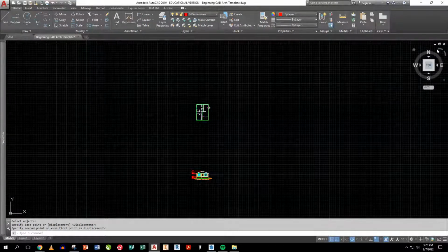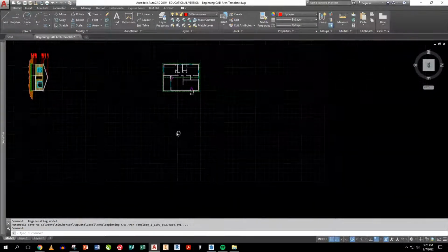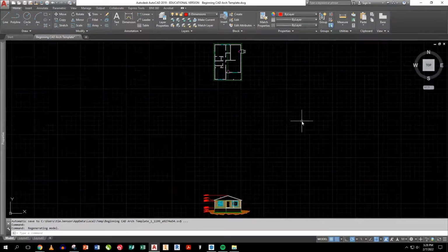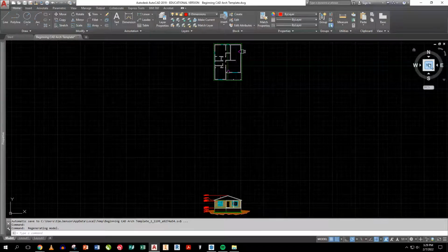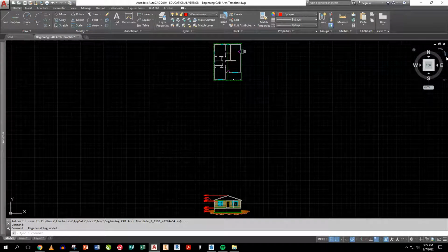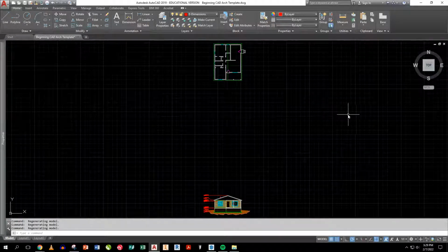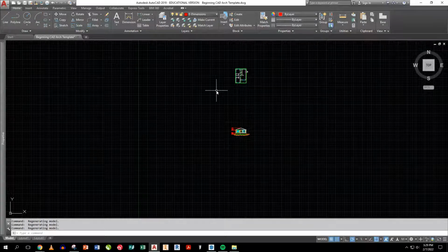There are some students that prefer to do this right here. If you click on the navigational bar, you can actually rotate it flat to you and project flat, and then rotate it back to normal. Okay, do not mess with the cube though. Okay, just a warning, because otherwise you could very likely end up drawing in third dimensions, and it just causes havoc for you. So those 2 rotational arrows right there are great to use if you so choose, but be careful not to mess up your other stuff.